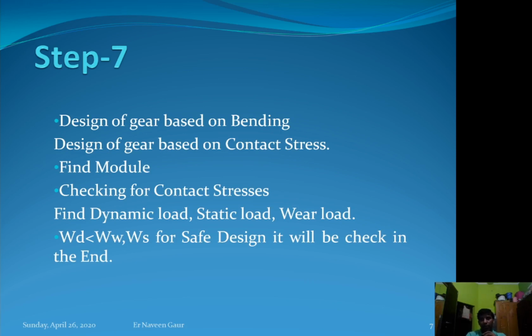The red spots show you the bending stresses and the contact stresses on the gear. So in design, we have to reduce these bending stresses and contact stresses as much as we can. For design of a gear based on bending, we have to find out the module first. And for design of a gear based on contact stresses, we have to find out the dynamic load, that is